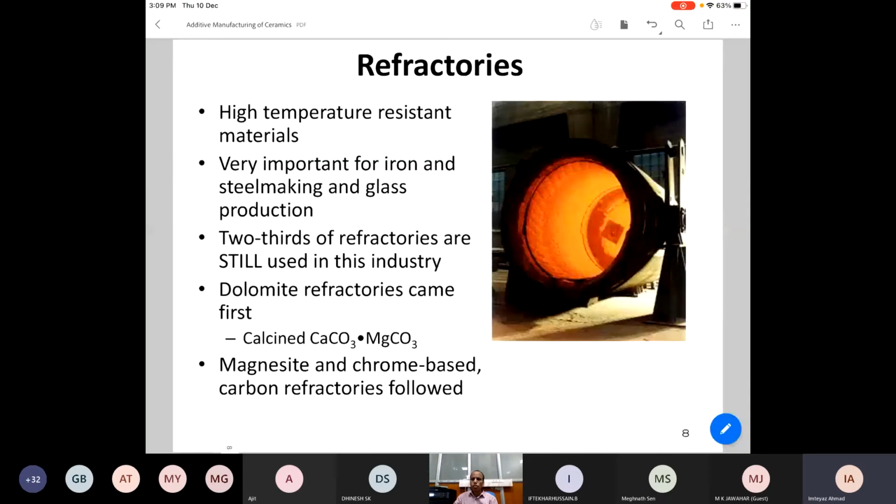Then you have refractories. These are very, very critical: if you do not have refractories, you will not have good metal. That's for sure. The reason is metals require 1500 or 1600 degrees C temperature for processing and purifying them. And to do that, you cannot have a metal pot, because they will react. Most metals melt or become very fragile, very mushy at those temperatures. So you need something which can withstand those temperatures without breaking, without yielding, and at the same time is chemically inert to the processing that you do, or the ingredients that you use for making slag and so on and so forth.